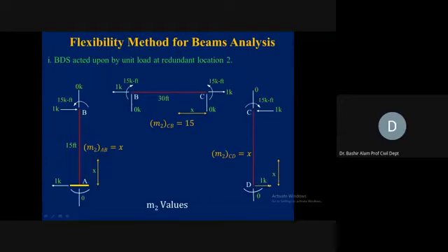So rightward directed 1 kip we are applying at D now. Because of this, we are analyzing the whole members and the whole joints. How will we analyze CD? This was 1 kip rightward directed, so at C it is 1 kip leftward directed. Horizontally, the members are in equilibrium now. Vertical 0 here, so 0 we have here also.